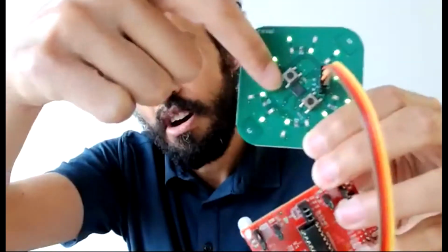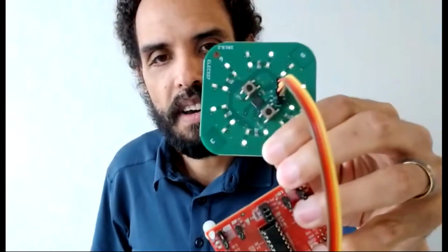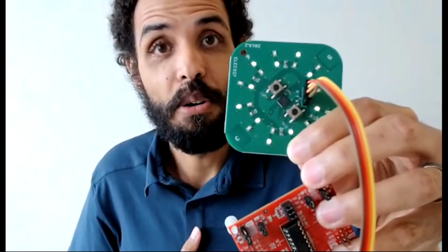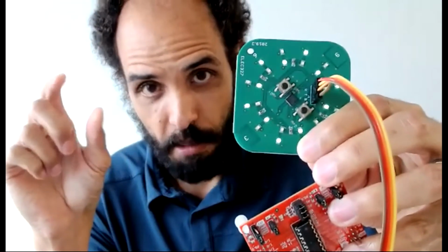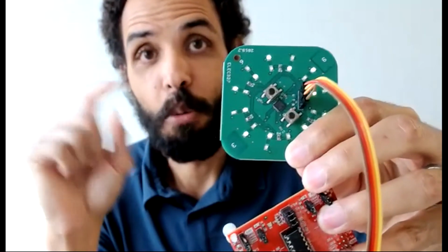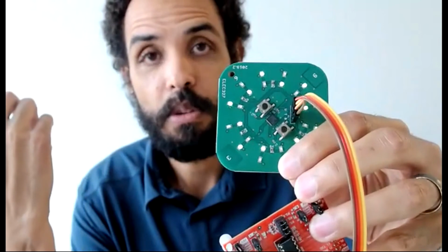I think I've posted already on Slack a link for the schematic for this board. It's exactly the same as the one that you guys are putting together, except that these buttons are connected to port 3, which is available on this 32-pin device. Turns out that port 3 doesn't have the port IO module, the port interrupt modules. So the sample code that you guys have for your boards, which will allow the board to go into low power mode 4, which means it turns off completely, it's waiting for a button interrupt, won't work on these boards, unfortunately, even if you modify it. So you can't just modify it to change those things to being port 3 interrupts.